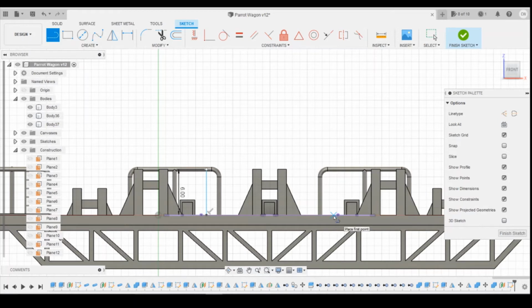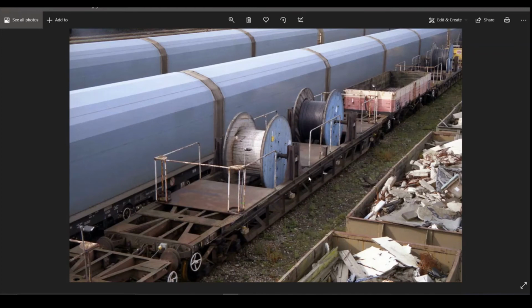Do the same on the side here, 6 millimeters. And we need to define the distance from the hole to the initial line. Let's go for 0.6 millimeters, I think. And we'll do the same on the other side. So there to there, 0.6. Okay, and then we have a line that goes across from top to there. So that fills in that hole. Okay, we've got 2 uprights.